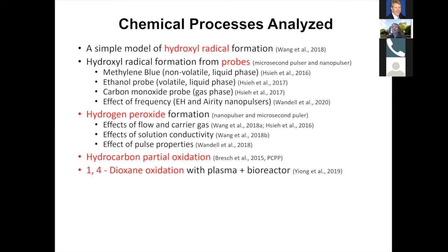But that also leads to an important application that Dr. Tang and his graduate student at the time, Dr. Young, worked on in terms of 1,4-dioxane oxidation. In that study, we combined the plasma reactor for the initial oxidation and a subsequent bioreactor for the final degradation of biodegradable products.